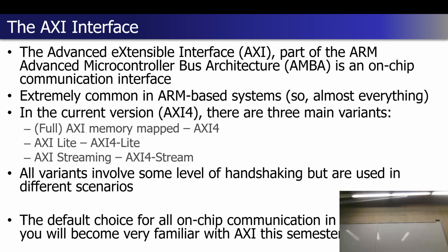This topic is we're going to talk about the Advanced eXtensible Interface, or just the AXI bus interface, which is directly related but not meant to be a replacement for the concept we were talking about last week. This is an example of a specific standard for communicating in embedded systems, and we can look at their solution to the handshaking problem. This solution matters because we want to build systems that are fluent in this bus protocol,